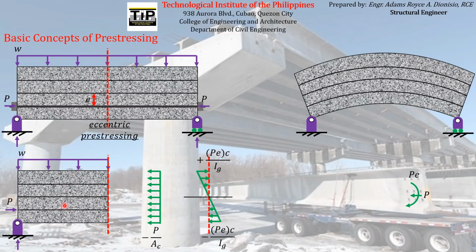And if we look at the free body diagram, due to that applied uniformly distributed load, there will be internal forces being produced inside the concrete beam on this particular cross-section. And again, what are those internal forces or internal moments? Obviously, this applied load will produce a shear force on this particular cross-section, which is the summation of the shear stresses acting on the cross-sectional area.